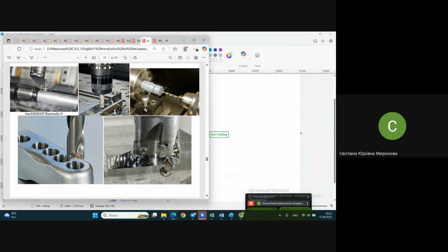That is in particular so-called end milling. Here is face milling, when the mill cuts the surface, but certainly it comes about as a combination. You see cutting edges, these blades in the view of cutting inserts, they may cut both the bottom and the side, of course.